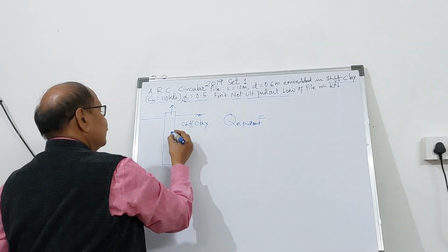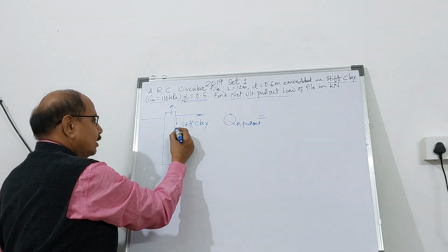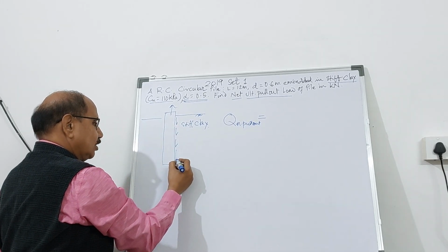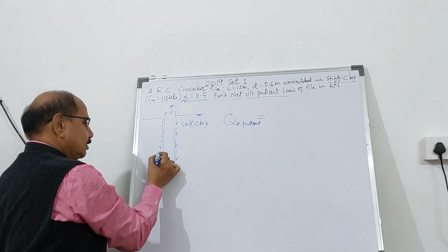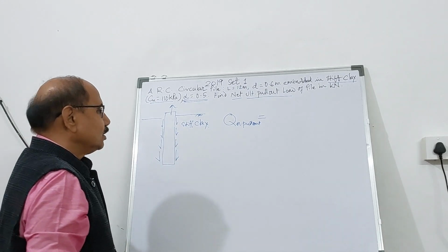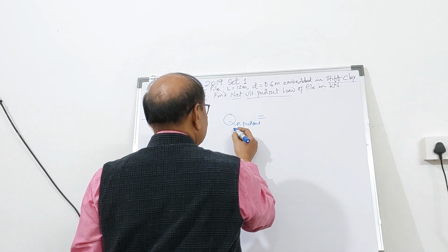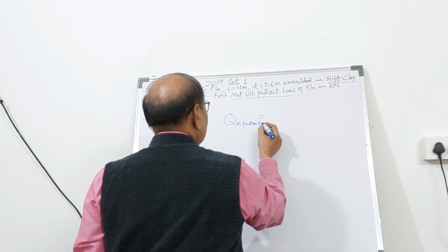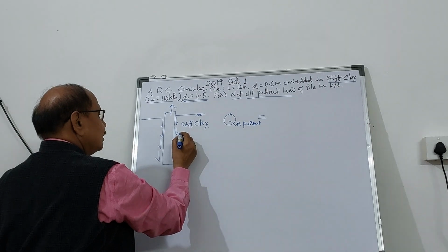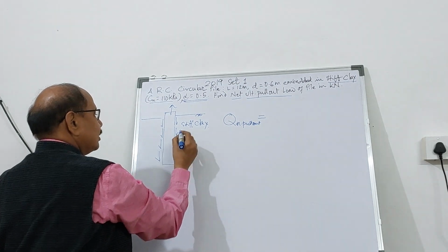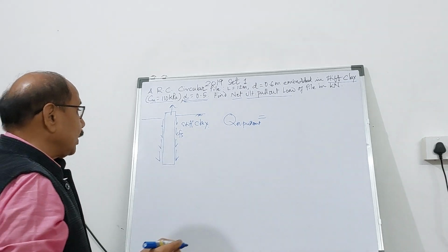will be, the moment you are going to pull this pile up, there will be a frictional force acting on the pile like this. So you need to calculate this frictional force which is going to act on this pile. So the net pull-out capacity will depend upon this frictional component. So what is this frictional component? Unit skin friction, that you should be able to calculate.